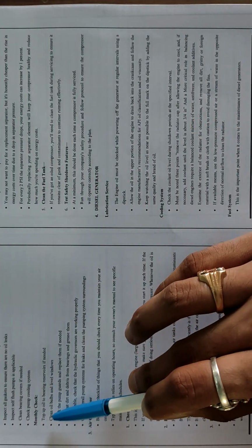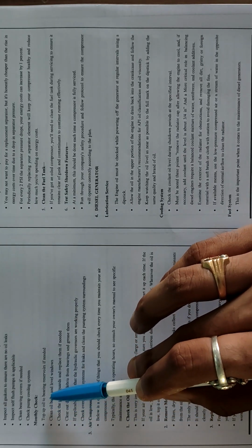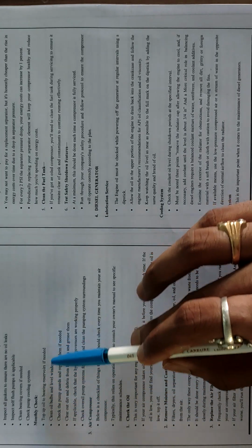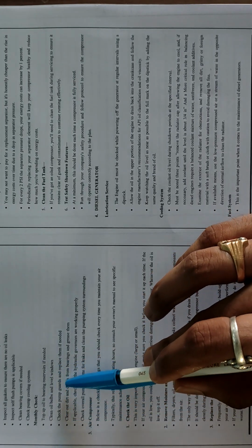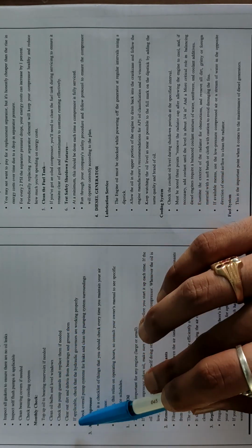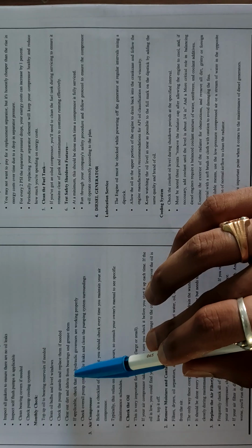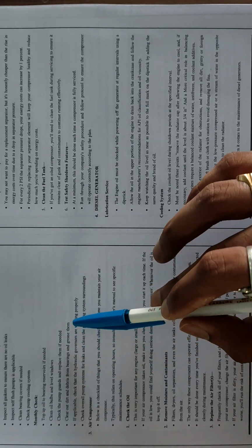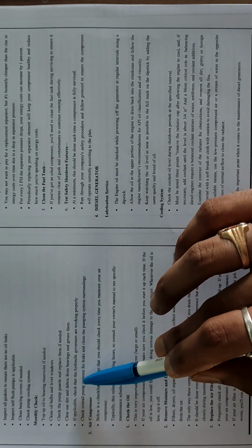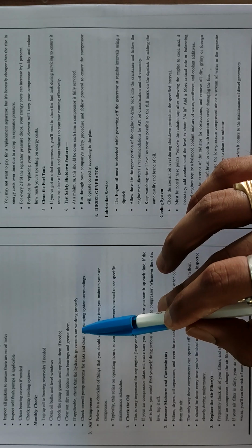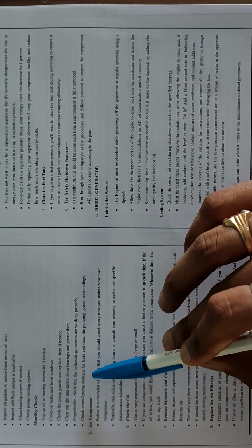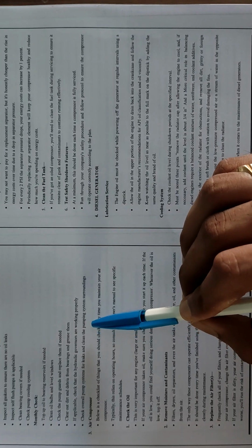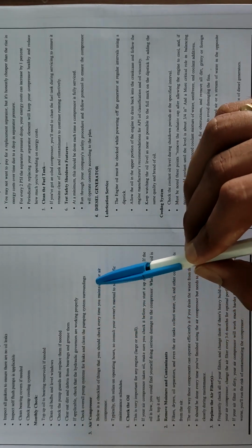Monthly checks: top up oil to bearing reservoirs if needed. Clean oil bulbs and level windows. Check the pump guards and replace them if needed. Clear out dirt and debris from bearings and grease them. If applicable, check that the hydraulic governors are working properly. Check overall pump systems for leaks and clean the pumping system surroundings.